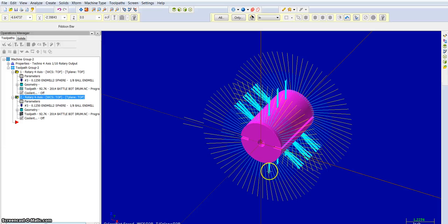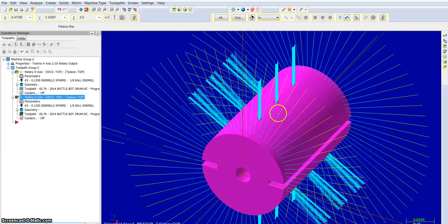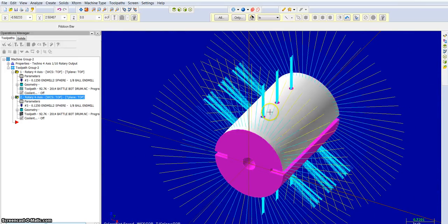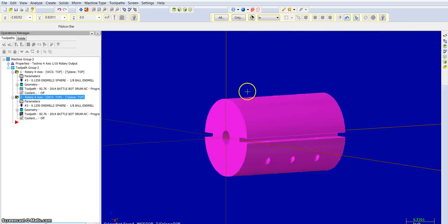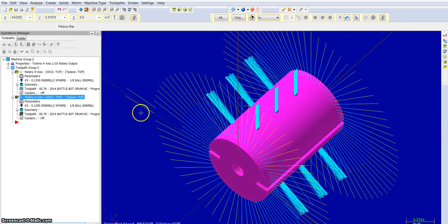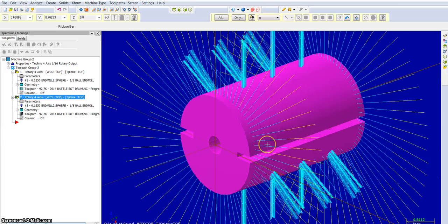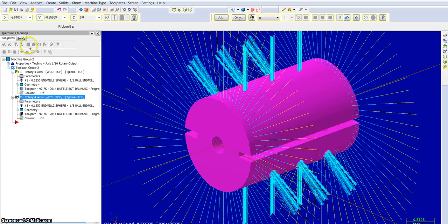That creates the toolpath. You see these portions in here where it's trying to plunge into those holes, which maybe we might want a little bit smaller bit. And if we wanted to see this, we have to go into backplot.